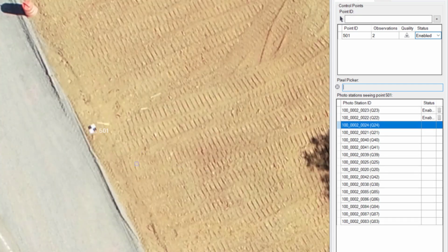If you prefer to use a dynamic pixel picker, you can use Control and Shift. And when you do this, your cursor becomes directly a magnification, and then you can move it. I currently move the mouse, but you can also use the keyboard arrow keys, left, right, up and down, to move it by a single pixel.